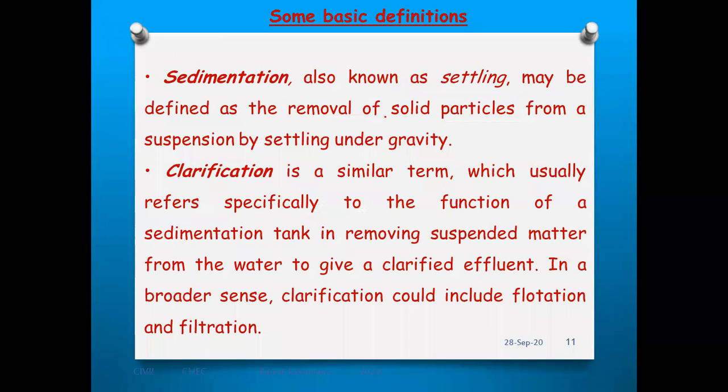Next thing, sedimentation. The next topic we'll discuss is sedimentation. So what is the meaning of sedimentation here? It is nothing but a settling thing. Whenever the water is flowing from the chambers, it will settle at every chamber for some time, right? So this is nothing but a settling of water. This may be defined as a removal of solid particles from the suspension by settling under gravity. So what is sedimentation? It is a process of removing the solid particles from the suspension by settling under gravity.